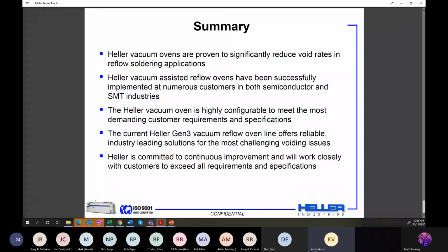by using vacuum reflow, you can definitely reduce voids. I guess the biggest thing that we're seeing is repeatability. Customers will come to us and they'll run along at 15%, 20%, and then their voids will jump up to maybe 30 or 40. So definitely, for repeatability and reliability, reducing voids needs to be done using vacuum reflow, and that's really it, Matt.